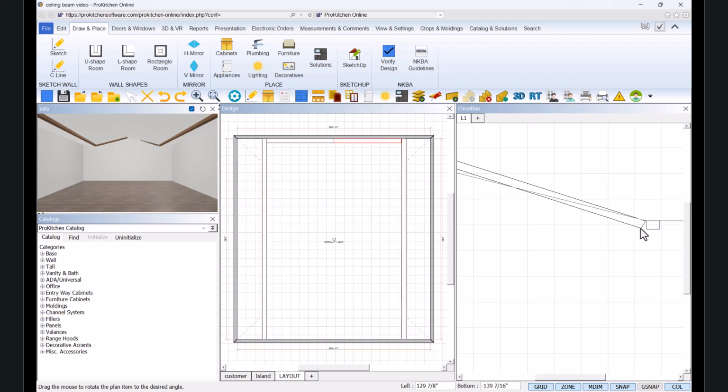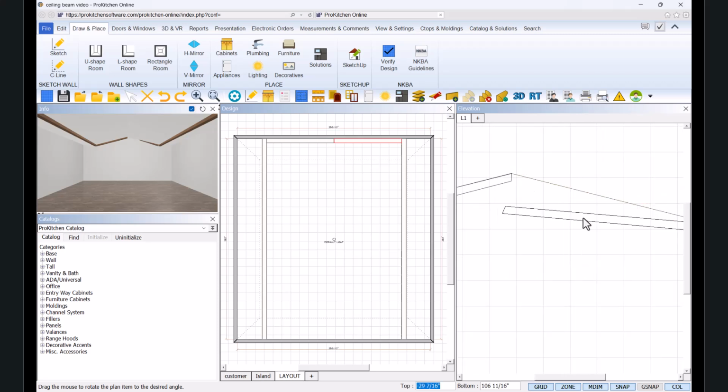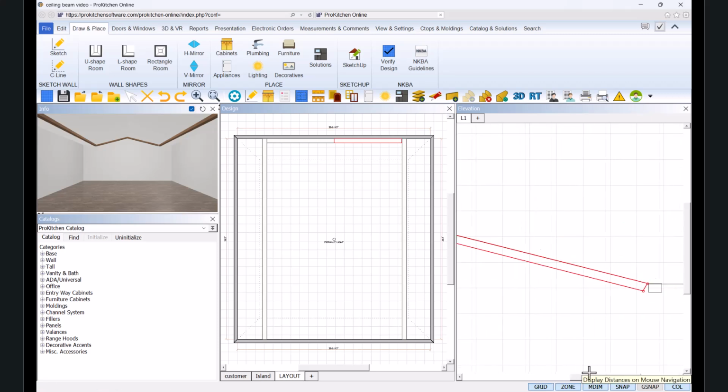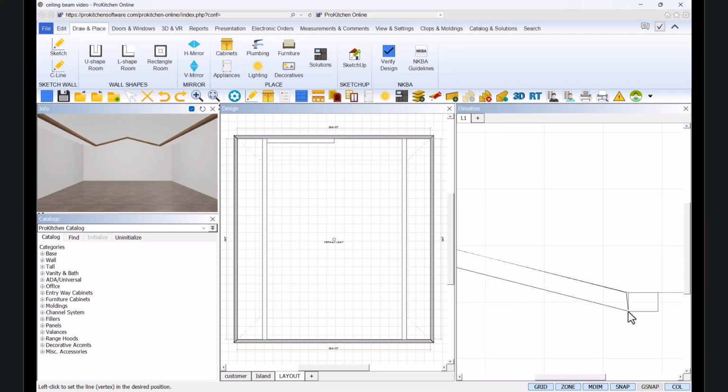We can do this manually with a left-click and hold, or by moving the item with the up-down and left-right movements as previously demonstrated. Once the right end top corner is sitting at the top left corner of the existing beam, we may rotate once again to match the rise of the slope. Access and use the Edit tools again to make adjustments to the 45-degree mitered ends so that both ends of the user shape match up to the existing item's vertical edges as previously demonstrated.